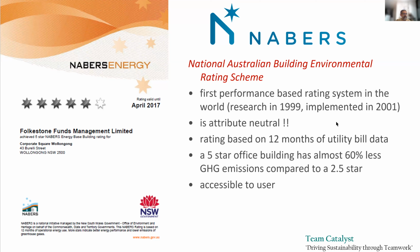So in the way that it assesses a building, it's quite neutral to what kind of air conditioning system you might have, what sort of glass you might have, what control systems you may have. It doesn't really care. What it does require is for you to provide 12 months of your utility bills and some data on the area of the building and how many hours it's being used for and so on. And that gives you a star rating.